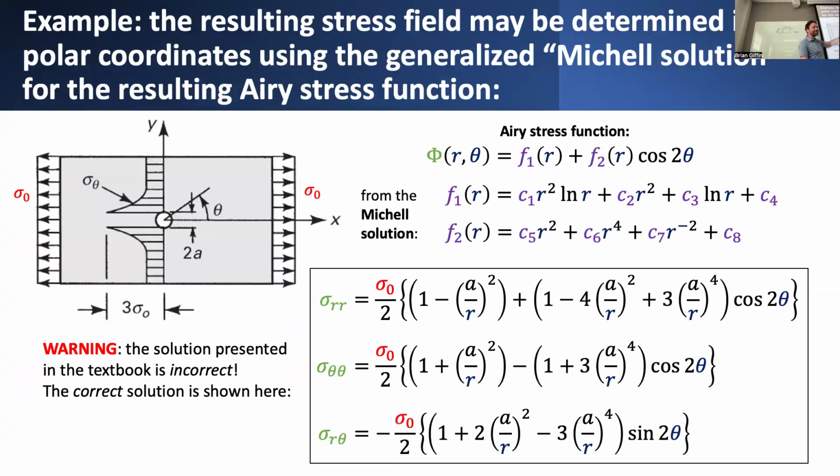Basically, it's already illustrating more or less what the stress distribution should look like. If you were to consider in profile what the stress distribution looks like along this line segment, far enough away from the hole, you would expect that value of stress in the axial XX direction to be roughly proportional to sigma naught, the average stress applied to the boundaries of the plate. But as you get closer and closer to the edges of the hole, it starts to increase.